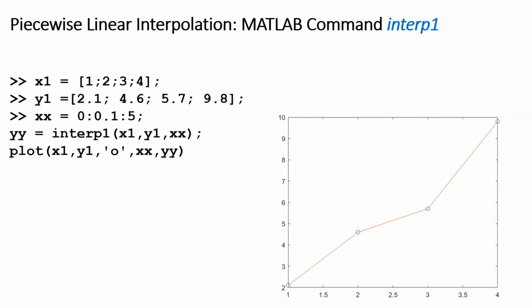There are other ways of interpolation in MATLAB, especially when you have to fit your function through many data points. Here, the one-dimensional piecewise linear interpolation built-in command is shown. The same data points x and y are used here, and interp1, where 1 refers to one-dimensional interpolation, is used.